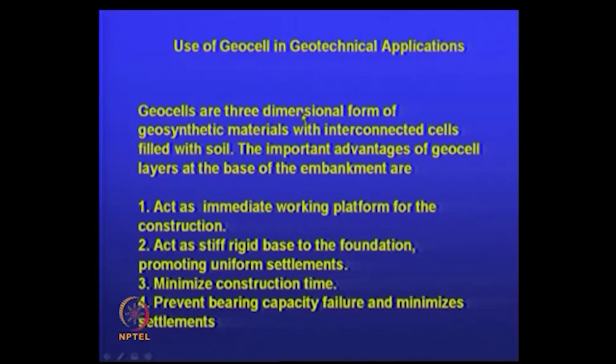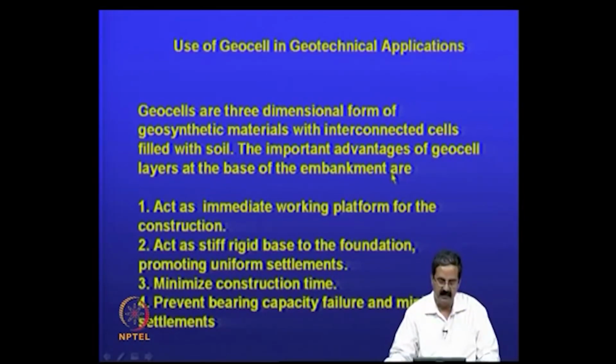In this lecture on design of embankments on soft soil using geosynthetics, we would be seeing the use of geocells. The geocells are a three-dimensional form of geosynthetic materials with interconnected cells filled with soil. It can be stone or even a marginal material like fly ash. The important advantage of the geocell layers at the base of the embankment is that it acts as an immediate working platform